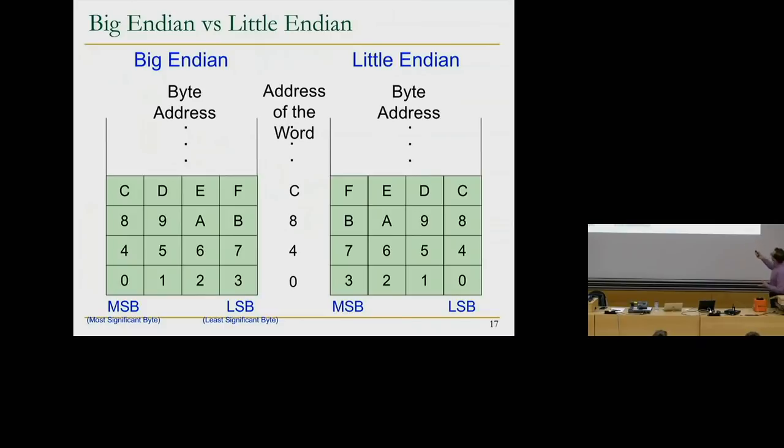Little endian means the most significant byte has the higher byte address. So the most significant byte has address 3, the least significant byte has address 0. You can see that that's true over here. Okay, so you'll deal with little endian machines. And I like little endian machines more because I somehow think this is more intuitive, because this is least significant, so it also has the smaller address. But there's really no correspondence. This is really by convention, right? You could easily think this way also.